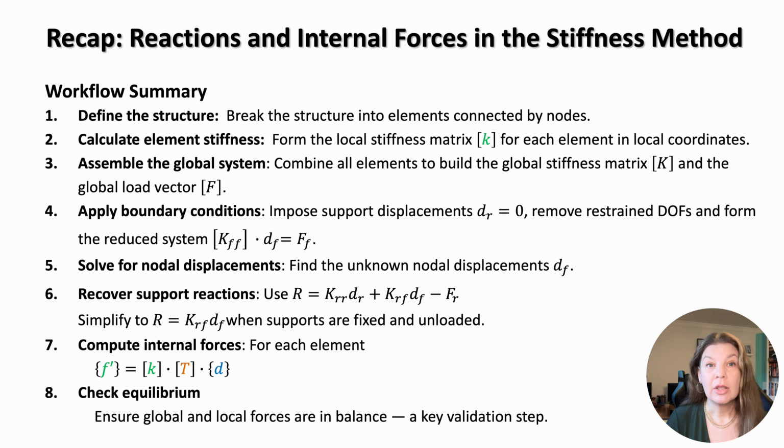workflow. The process begins by dividing the structure into elements connected by nodes and calculating the local stiffness matrix for each element. We then assemble the global stiffness matrix and load vector, apply the boundary conditions, and solve for the unknown nodal displacements. From there, we can recover the support reactions and compute the internal forces for each element using the relationships we've already derived. Finally, we can check equilibrium to make sure that the structure is consistent, that the global and local forces balance. In summary, everything on this slide is a workflow summary of the method we've already developed theoretically.